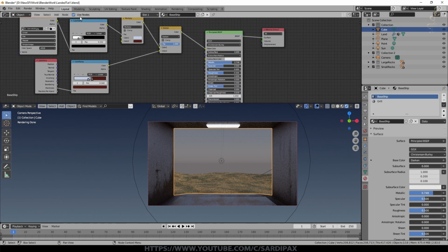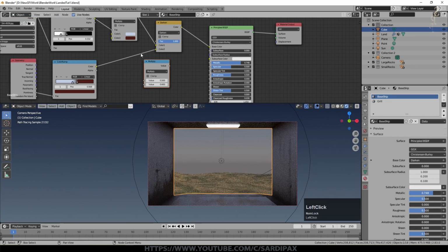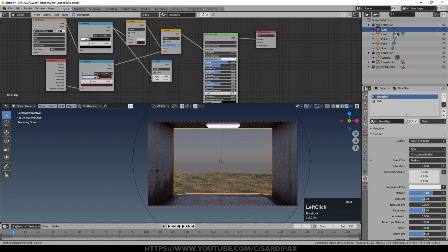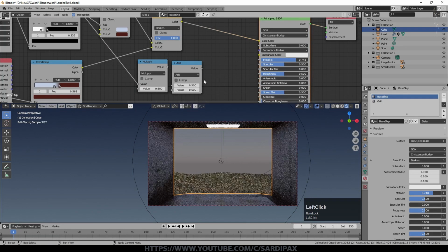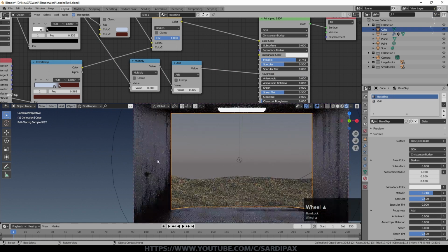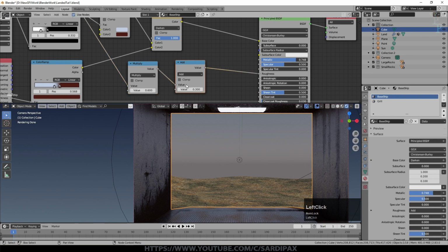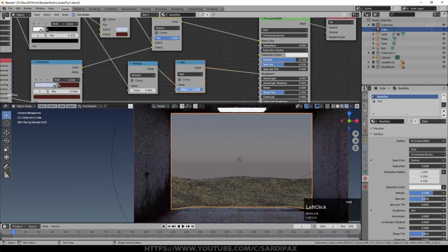accumulating dust and dirt. So I'm now going to add a converter, which is a math node. Set that to multiply. Have the lower value at about 0.6. Take the output of my color ramp and put that into here. And I'm going to duplicate that math node, change that to add, and I used a value of about 0.3, and take the output and multiply into there. And then the output of that goes into roughness. So the idea being that certain parts of the material are a little bit shiny and other parts aren't. And again, I'm scaling it with this one and then putting an offset with this one. So if I increase that offset, the roughness will go up and it becomes much flatter, as it were.